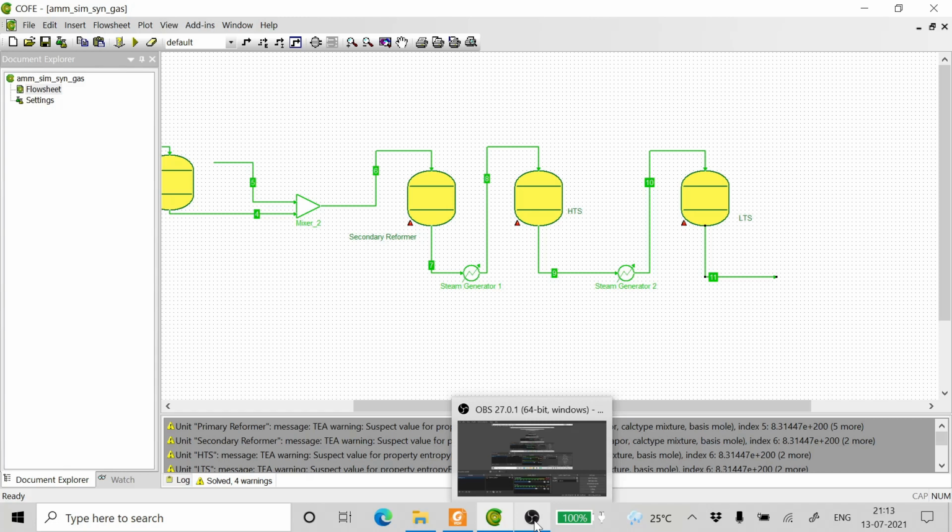So what we have here is that the stream that finally leaves the methanation reactor has very little carbon monoxide and carbon dioxide, and a rich amount of nitrogen and hydrogen and very little argon in it. And a very little amount of water too.